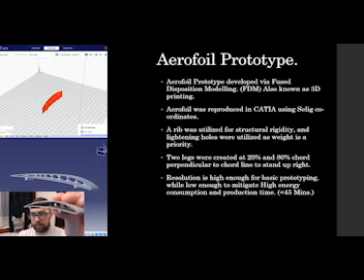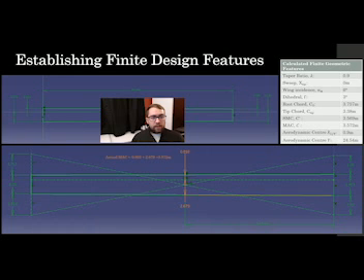As you see, wing tapering moves the centre of pressure inboards and lowers bending moments, but it also reduces lift and increases the risk of tip stall. How UAVs achieve lift at lower velocities and stability is vital, so a taper of 0.9 will be used.